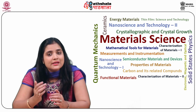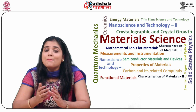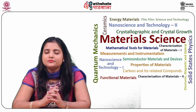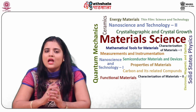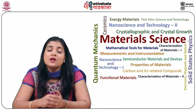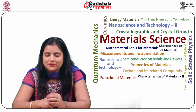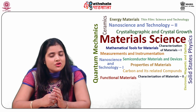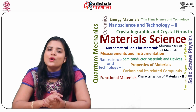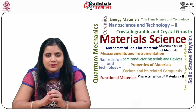Secondly, the resistor used for the MSB is required to handle much larger current than that used for LSB. For example, in a 10-bit system, the current through the MSB resistor is 500 times that through the LSB resistor. Because of these shortcomings, it is preferable to make a circuit which uses fairly close values of resistances.